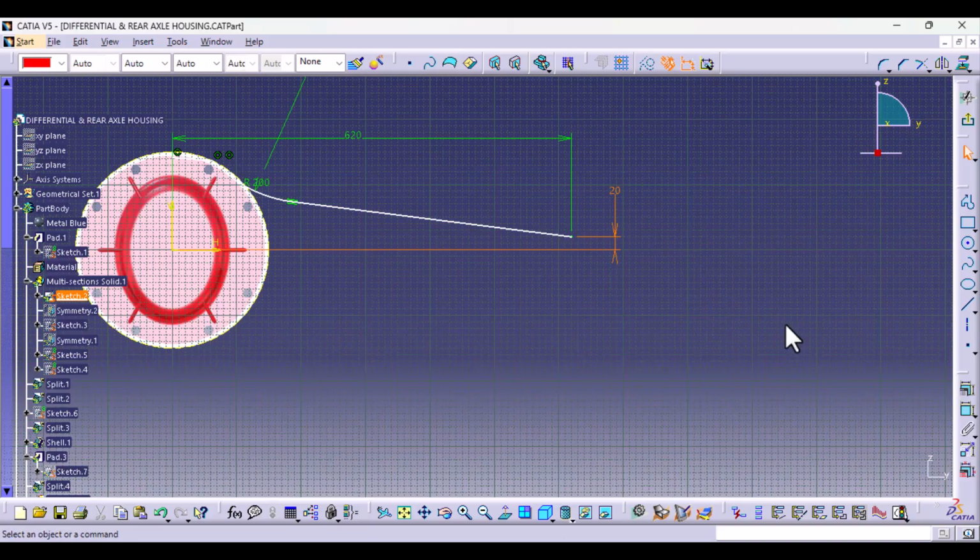That's the first one. And then I want the distance. I want to make something clear. We've got some edge fillets at this section. I want to keep this section exactly the way it is. I don't want to move it or change the radius. I just want to constrain the distance between this point and the horizontal axis. Between that point and the horizontal axis, and I'm saying I want this distance to be 60, like that.